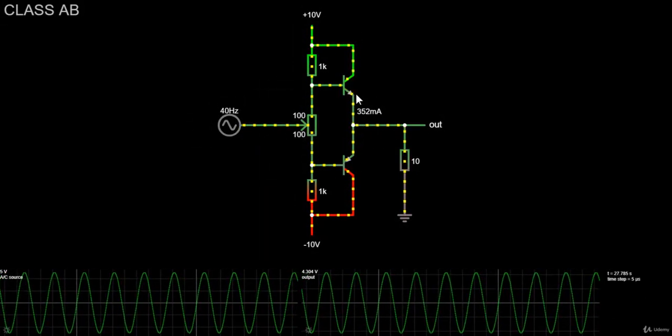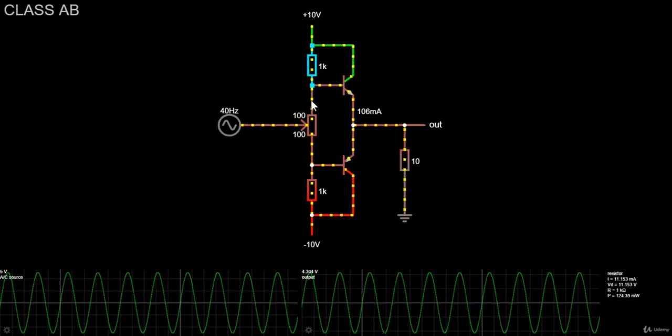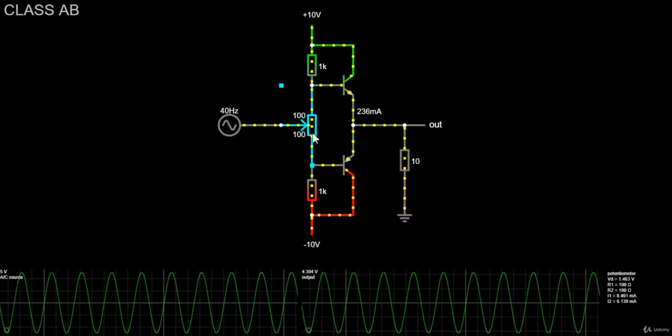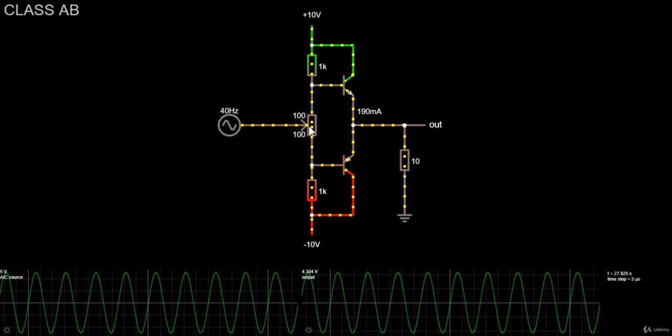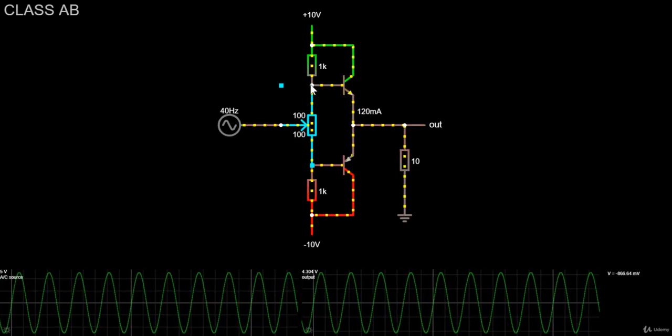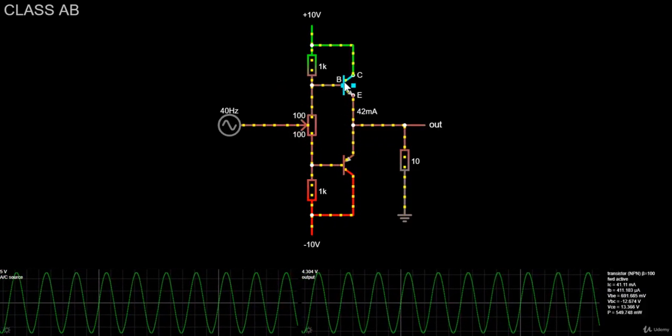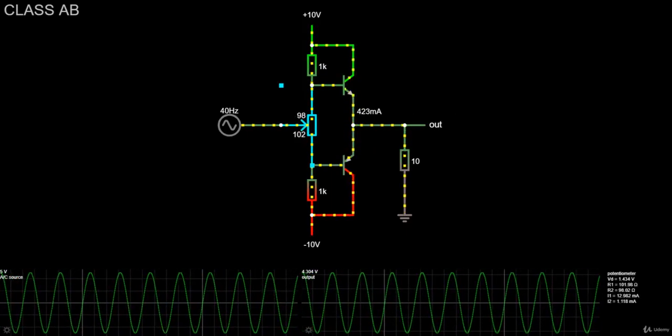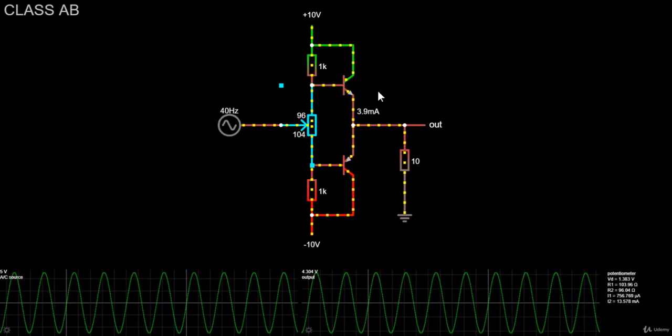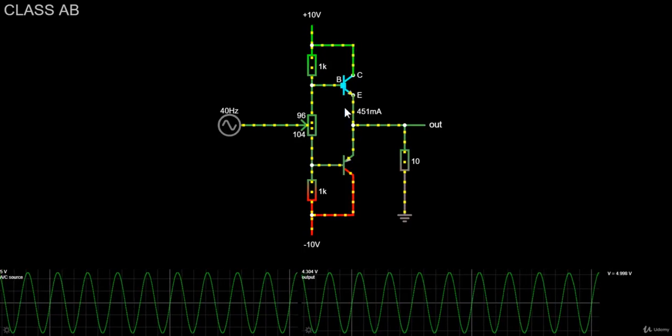This method is very similar to the voltage divider network. The only difference is that an adjustable resistance, or potentiometer, is placed between the two networks. The advantage of this solution is to closely match the biasing of the two complementary transistors with a controllable resistance, even if the transistors have different electrical properties.